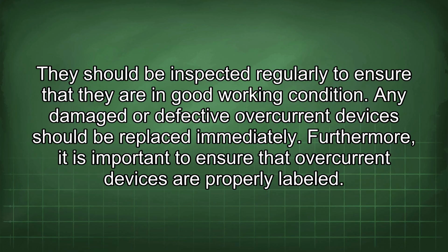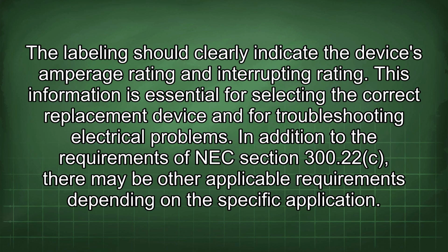Furthermore, it is important to ensure that overcurrent devices are properly labeled. The labeling should clearly indicate the device's amperage rating and interrupting rating. This information is essential for selecting the correct replacement device and for troubleshooting electrical problems.